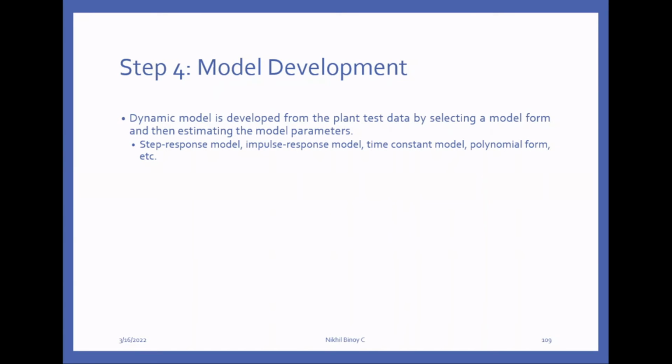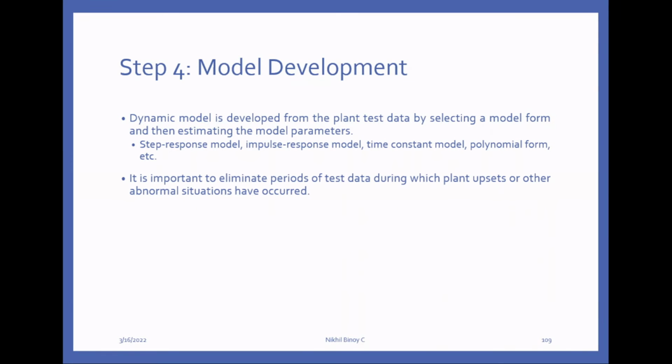We can develop any type of model like step response model, impulse response model, time constant model, steady state model, polynomial form, etc. But here in this particular explanation we are using step response model. In this one it is very important to eliminate periods of test data during which planned upsets or other abnormal situations have occurred, like control valve saturation.